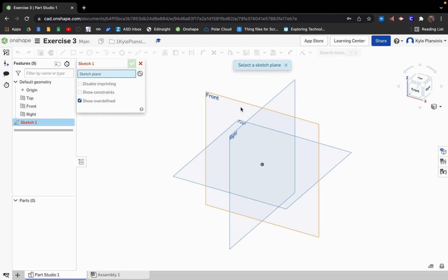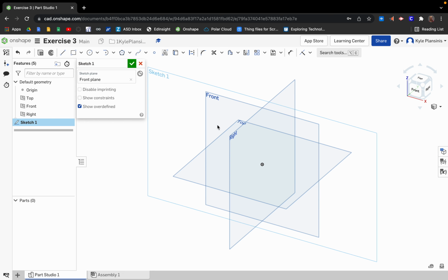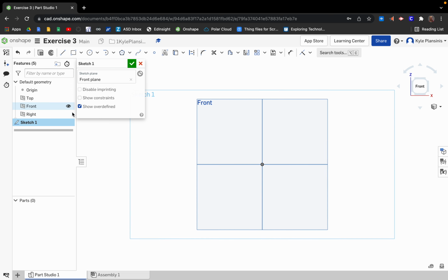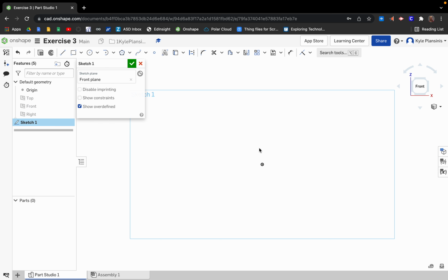And we've already used the sketch tool, so use your sketch plane, create it on the front plane, N for normalize, and I like to turn off all those fields or planes. You don't actually have to do that. I just think it cleans it up and makes it easier to understand. So over here it's just kind of somewhere away from our origin. And on your first couple drawings I had you anchor to this origin right away. And just to show you a few more constraint tools, we're going to start away from that.